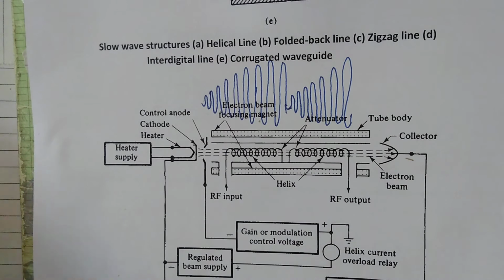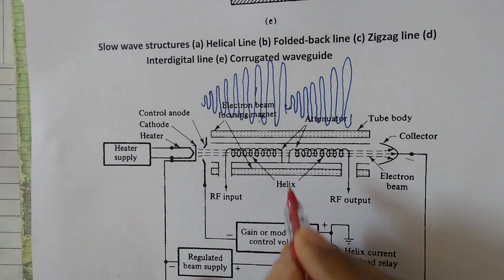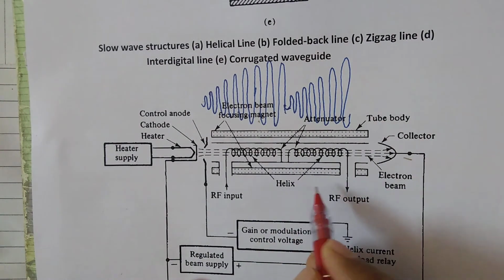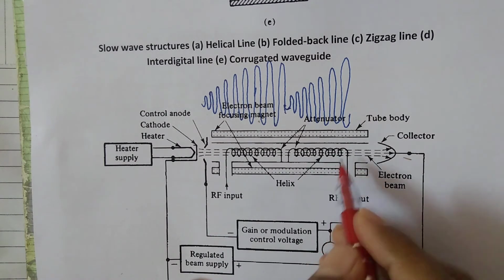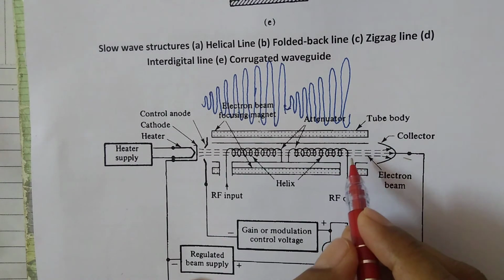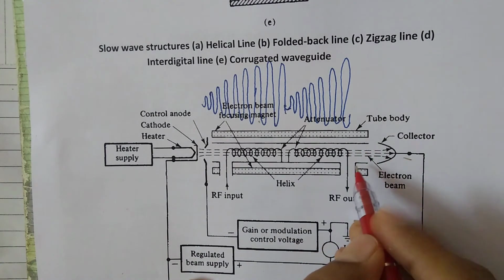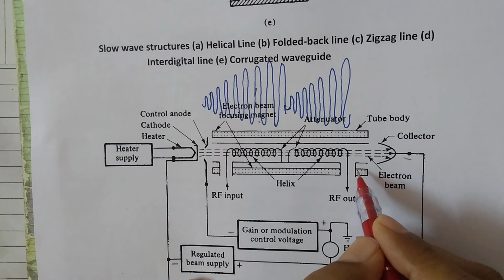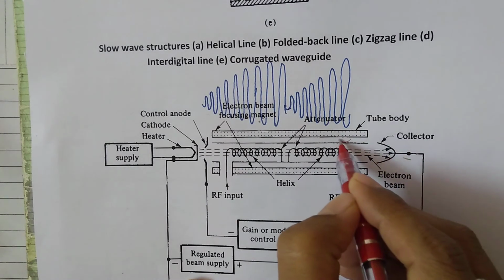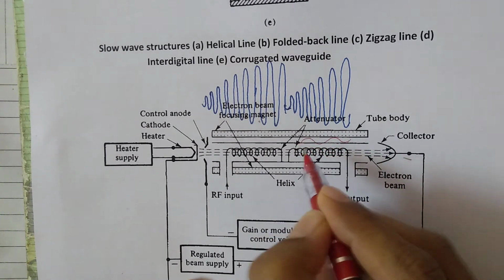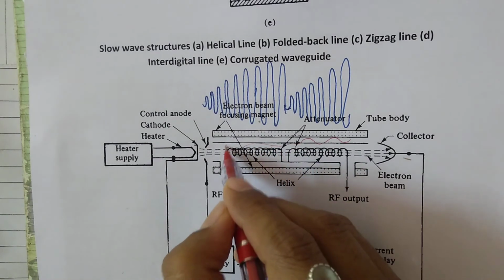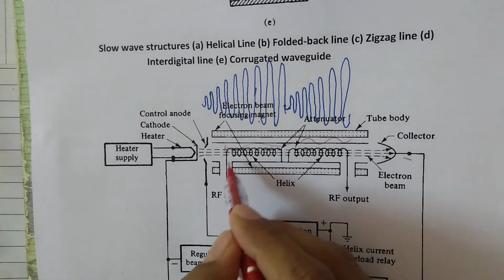The most important use of this attenuator is that, since at microwave frequencies impedance matching is very important, and since this is a high gain amplifier, if at the output there is an impedance mismatch and any signal reflects back and reaches the source, it can disturb the source.